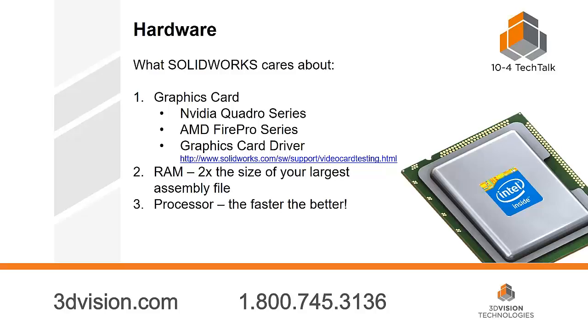Justin, can you just comment a little bit about multi-core, just to see if there's any benefit for customers about multi-core? Yeah, sure. So a lot of people ask about that when they're buying a processor. Should I get a multi-core processor that has 16 cores, or should I buy one that's only a couple cores and the fastest? I usually say get the one that's the fastest possible. Now, there are some applications in SOLIDWORKS that can use multi-cores, but the majority isn't a significant difference. So maybe if you do rendering or simulation, multi-cores will help you out. But in most cases, just get the fastest one that you can get at the time.